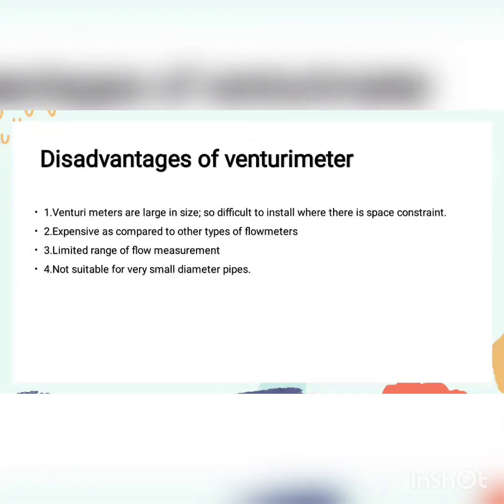Now coming to the disadvantages of Venturimeter. Venturimeters are large in size, so difficult to install where there is a space constraint. Expensive as compared to other types of flow meters. Limited range of flow measurement. And finally, not suitable for very small diameter pipes.